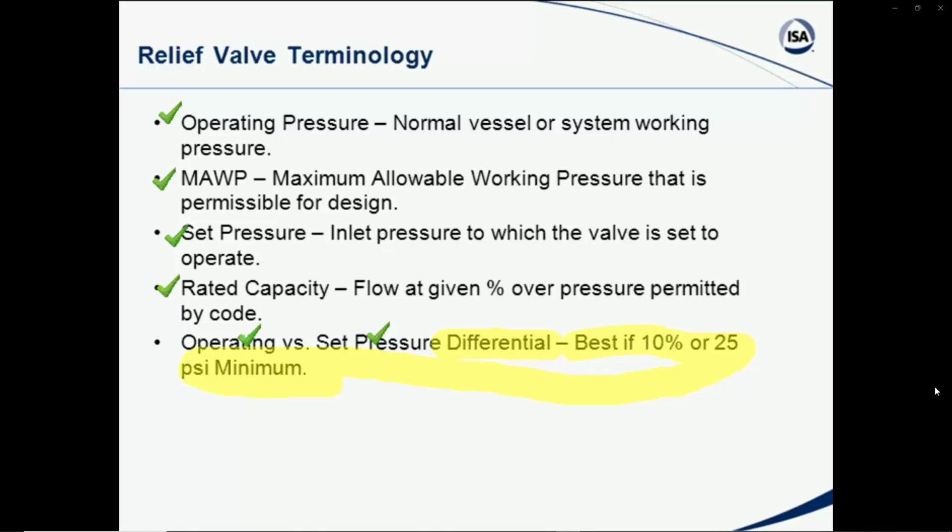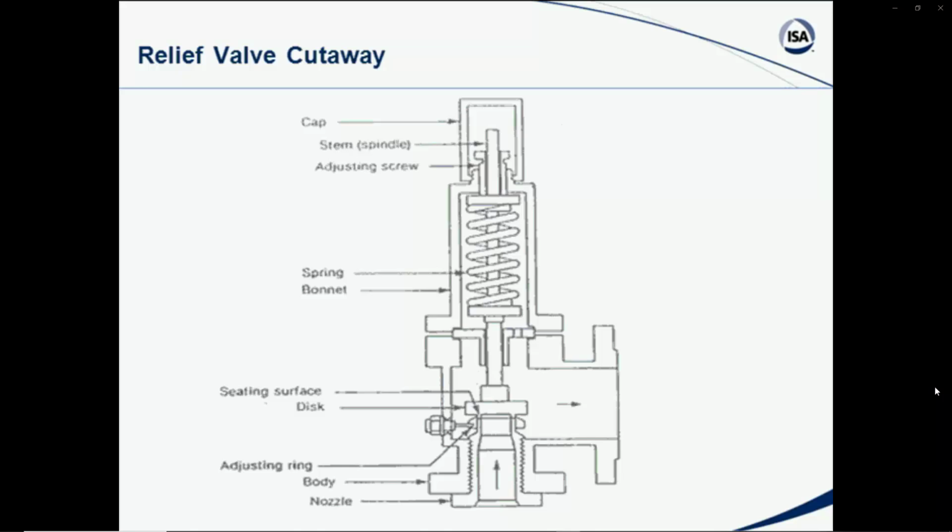It's running along too near the pressure, so it tries to open up a little bit. So whatever your operating pressure is, there should be a gap between that pressure and your set pressure, in order to allow the system to operate and yet maintain control at the same time. This is very critical as far as the terminology, and we'll try to clarify that in a moment.